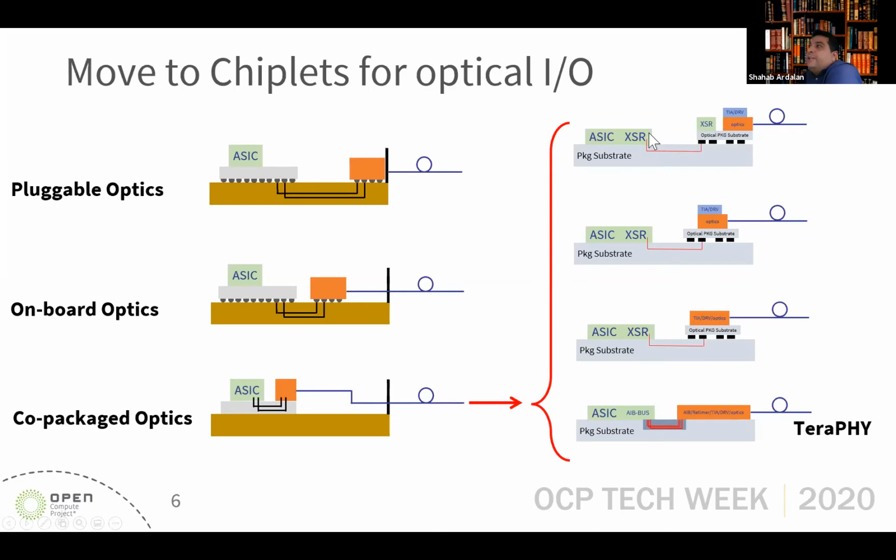One is actually having a kind of XSR link between these 2 dies, and then having an XSR over there. Again, optics is going to be on the orange, and we develop TIA and driver in different package. We do 3D integration and 2.5D integration between XSR and optics, and then basically connection another level of the 2.5D integration with the ASIC chip. This is pretty complex, a lot of stacking on top and connection.